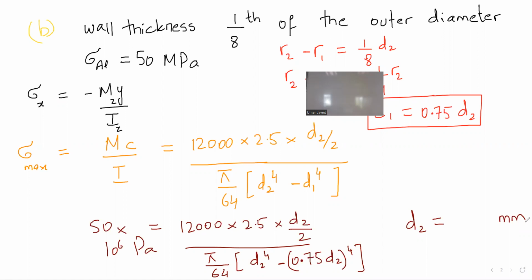I can remove the negative sign, and just by looking at the drawing, I can make a guess. When I'm pulling like this, this surface has tension and this surface has compression. You can put the negative sign at the end that this surface has compression and that surface has tension.